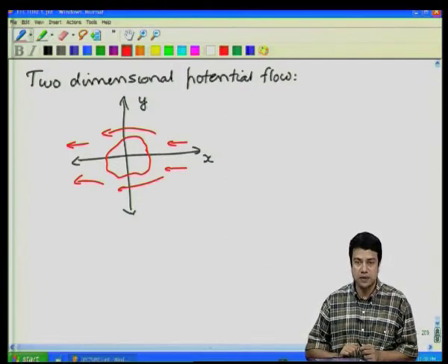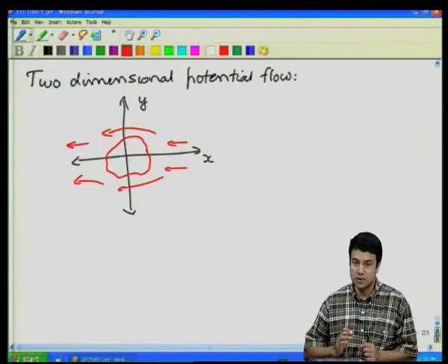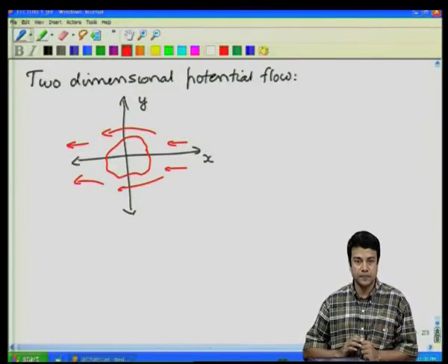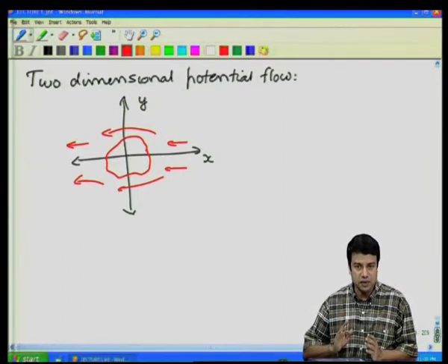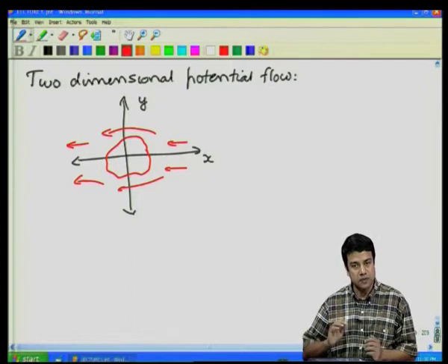So, all quantities that we will calculate, such as the force on the object or the energy of the flow, are all per unit length in the direction perpendicular to the flow. So, they will have dimensions of inverse length times what you would normally expect. In this case, for the force on this object, it will be a force per unit length in the plane perpendicular to the flow. For example, if you had a long cylinder and you approximate that cylinder as being of infinite length, you cannot calculate the total force on that entire cylinder. You can only calculate the force per unit length. That multiplied by the length will give you the total force.